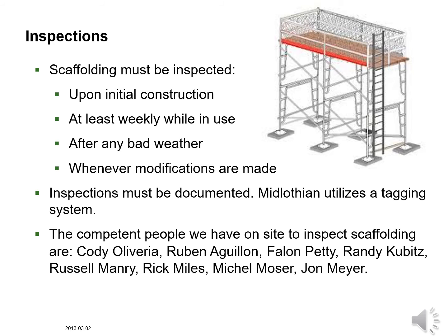Midlothian utilizes a tagging system which we will talk about next. If you get ready to use a scaffold in the plant, and notice that it has not been inspected in the last week, call one of the competent people listed on this slide to perform an inspection.